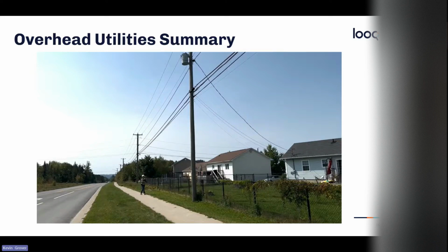This is where it's important to walk in the snaking pattern away, adjacent from the line. You see him doing a bit of a snaking pattern back and forth. It adds that bit of variation when you go from pole to pole. Then at the pole itself, if you can't do the next pole as the full capture, you see there's a lot of vegetation on the one side, you want to make sure we're walking the 2 parallel offsets or changing the height of the capture as you're walking as well.